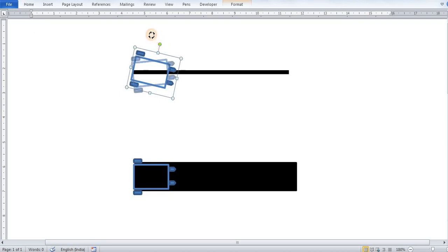In the opposite way, if by mistake our robot turns to the left, our right sensor will start showing black value. The left sensor will continue to show white value, and in that case, we should turn right. So whichever sensor shows black color, we need to turn that side. If the left sensor is showing black color, we need to turn to the left.